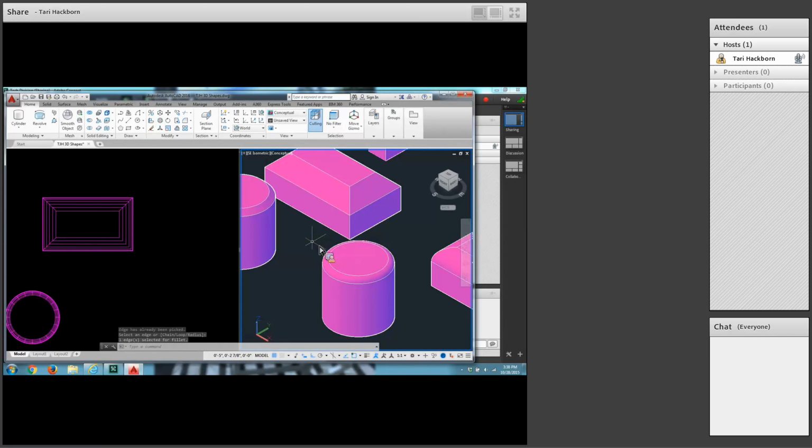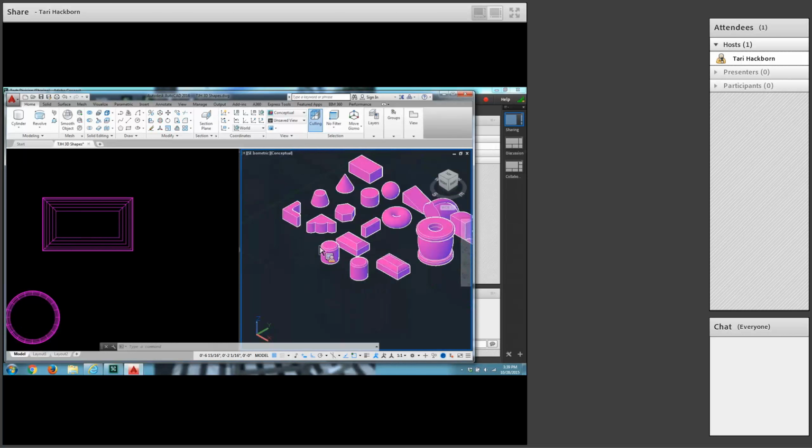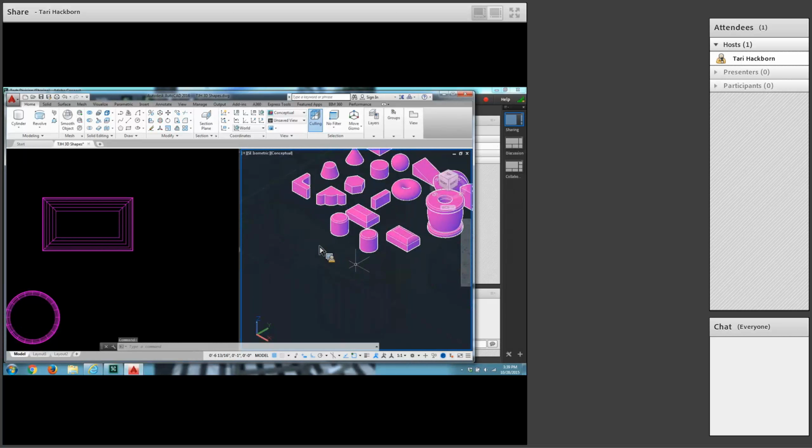Now we're going to make the part you see on page 63. This is the one where you're going to end up using the Boolean editing commands of union and subtract. On page 62, it says to type UCS and enter twice. That's just to make sure the UCS is in the correct location. Okay. So I will UCS enter twice. Okay, it is.